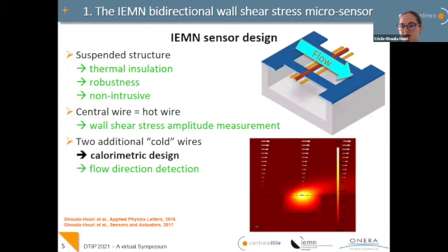But it is a point that needs to be measured, and it is one of the drawbacks of thermal sensors. In wind tunnels, when we are doing experiments, temperature and humidity are two main factors that we need to have in mind to compare experiments.